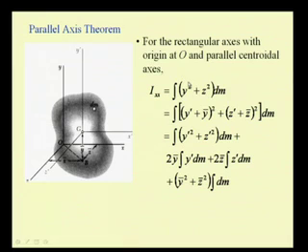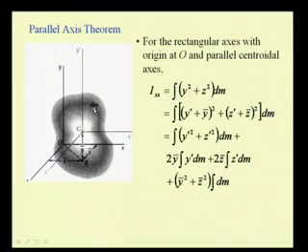Now, we write the y square and z square terms in terms of the centroidal coordinate and the distance of an element mass in the axis centered at the centroid. So, we are writing the coordinate of the location dm with respect to the transformed coordinate plus the distance by which it has been transformed.